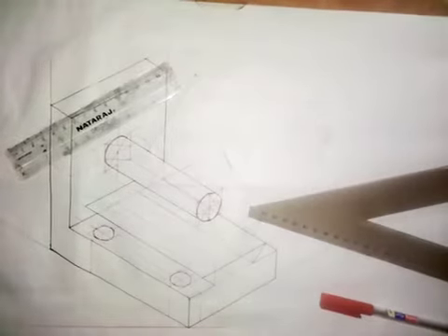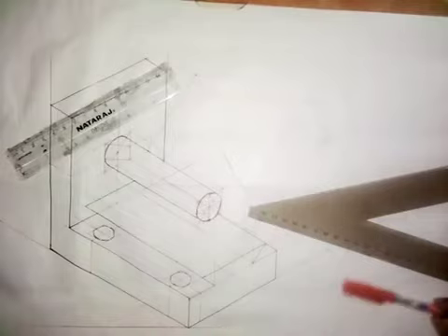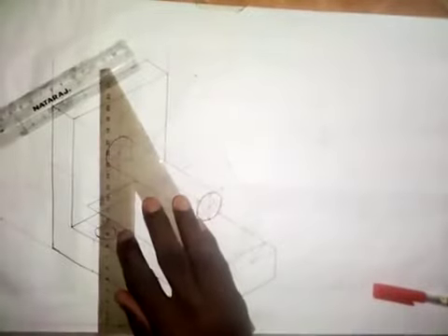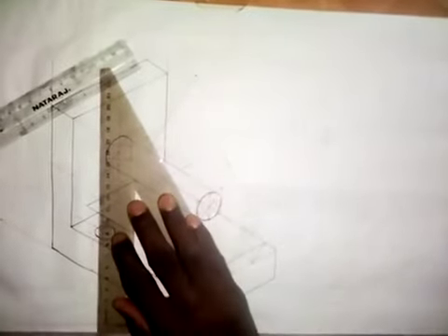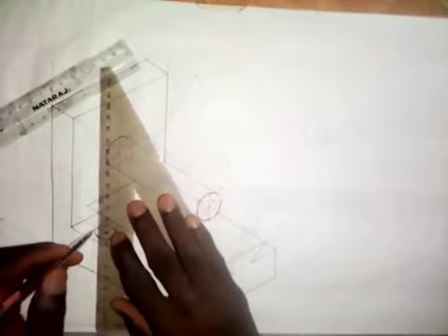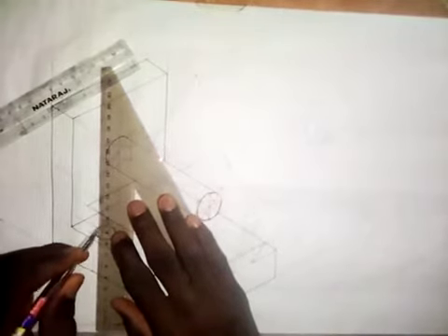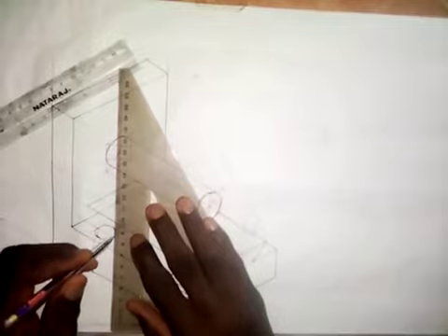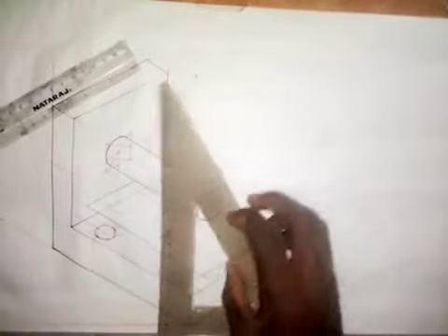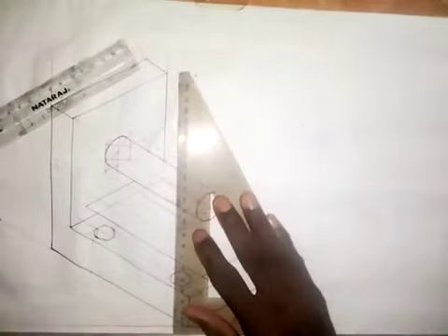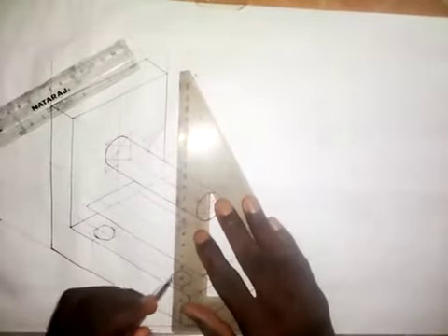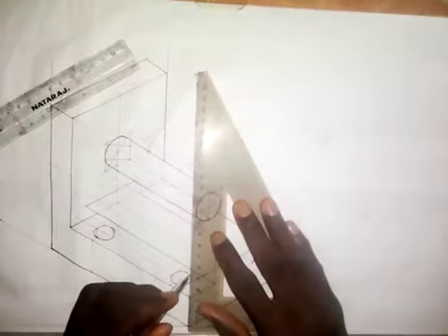All right, so we have formed the isometric circle. So the next thing I'm going to do is that we are told that the depth is 5 millimeters. The depth is 5 millimeters. So from this point, I will draw a vertical line down. And from this point, I will do the same thing. So draw a vertical line down here. Okay, so I will also come to this side and do the same thing. From this point, I will draw a vertical line here. And here also I will draw a vertical line here.